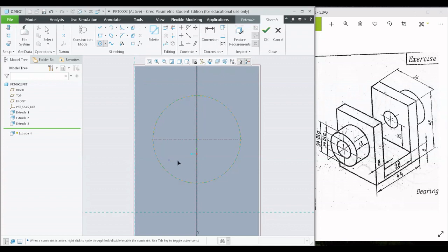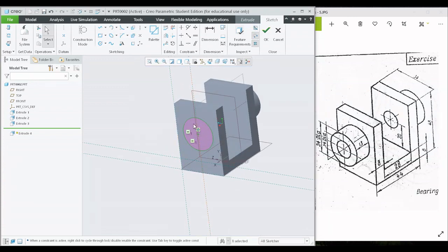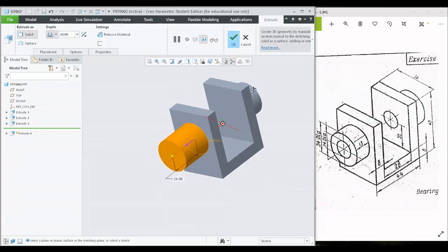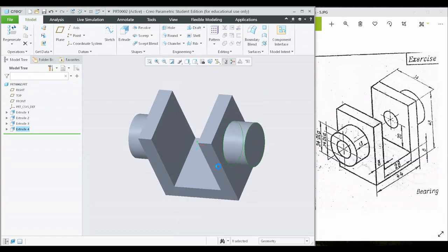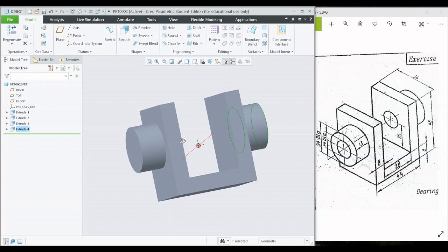We can just click over here and stop the construction. So we have the sketch over here and simply press OK. Now we have to change the extrusion length, and that was equal to 13 millimeter. Press OK and Control D. So we have the geometry ready with us, the simple part model.